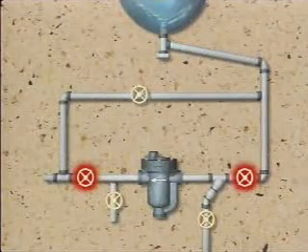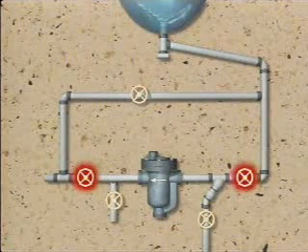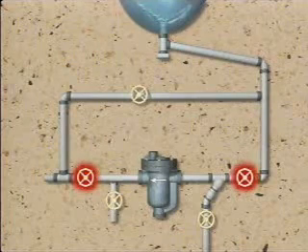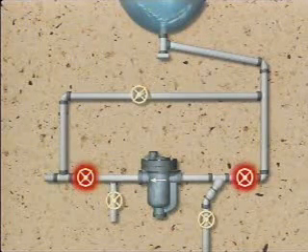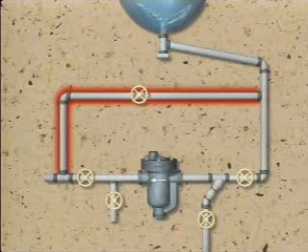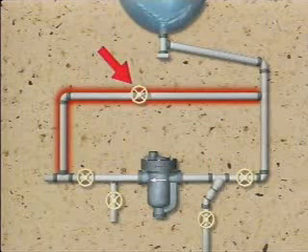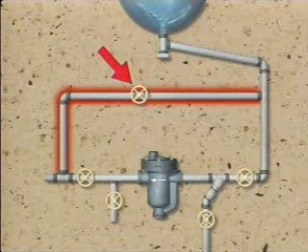The inlet valve and the outlet valve are isolation valves that can be used to block off or isolate the steam trap from the steam line. This is usually necessary when the trap must be repaired or replaced. A bypass line is also included in many steam trap stations. A valve in the bypass line enables workers to bypass the entire steam trap station if necessary.